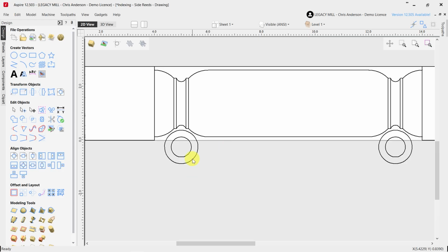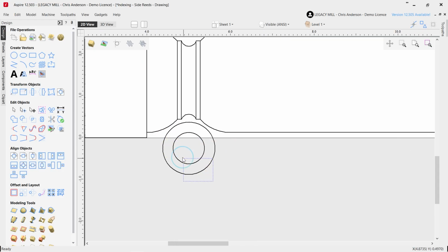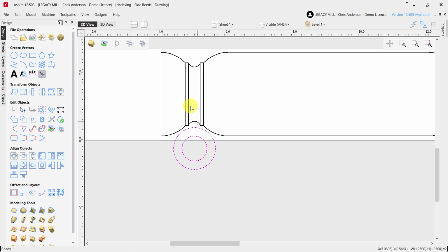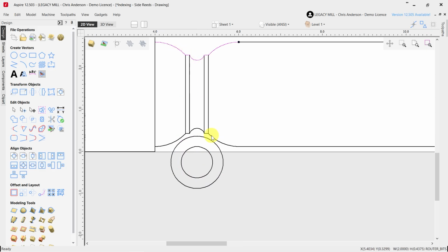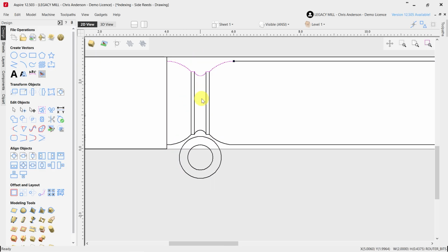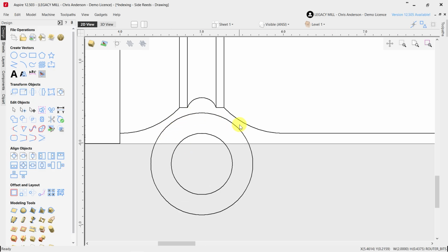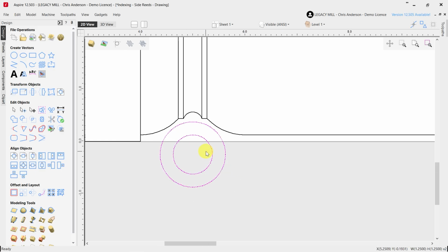Now, if we look here, if I simply make the start position the same as this profile cut that we did earlier, so that both the centers of the cutters are lined up at the same location on my x-axis, you can see that I have clearance to where the cutter isn't going to be hitting anything when it comes into the material at first. It will actually only start making contact with the material when it starts traveling down the part, instead of making contact with the material when it's actually approaching the material from the side.